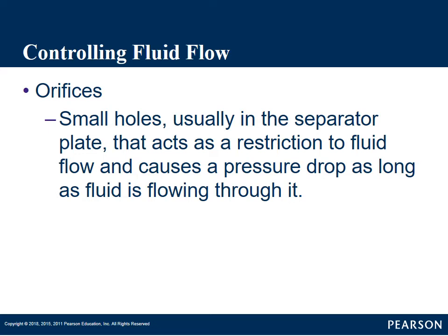That's used commonly when we're applying clutches. That's that big hole and small hole. We use that smaller hole so we apply the clutch slower and softer. That's for comfort reasons. There's some cases, like I said, in shift kits, you can take a check ball out. It'll apply through both those holes. It'll apply the clutch pack faster and harder.